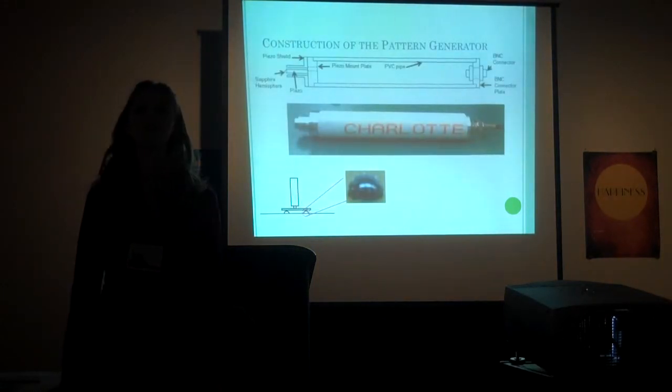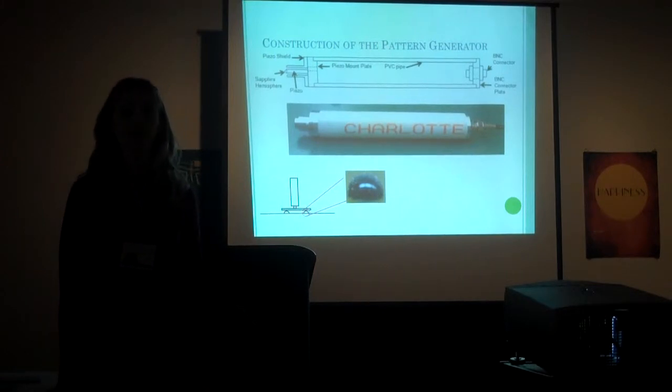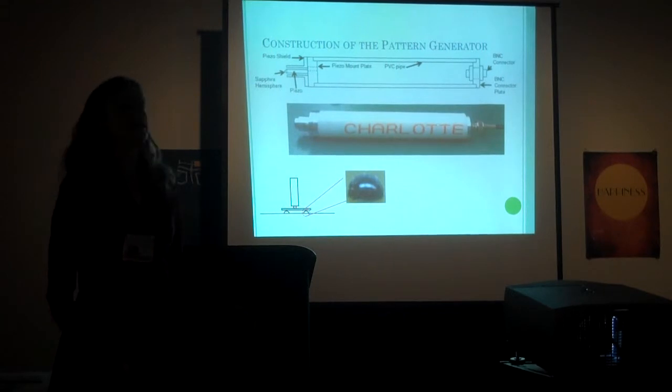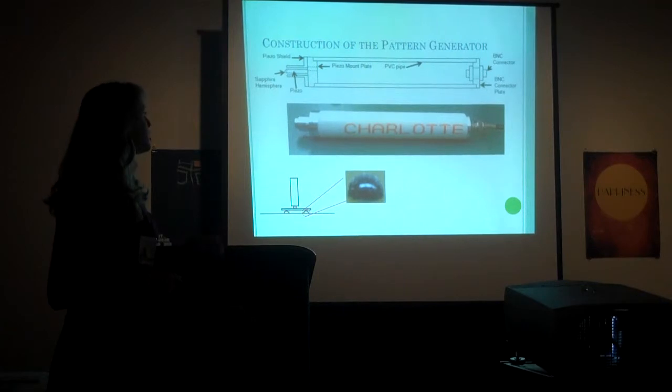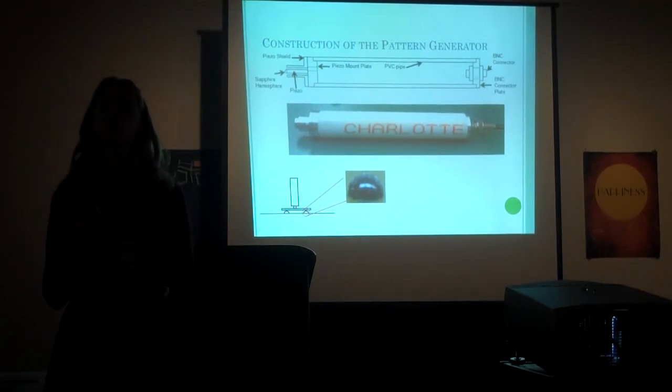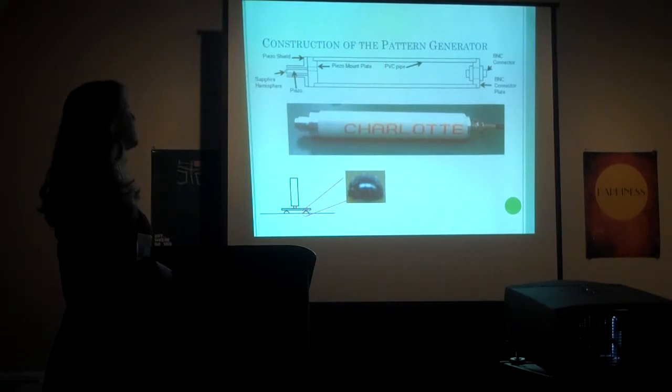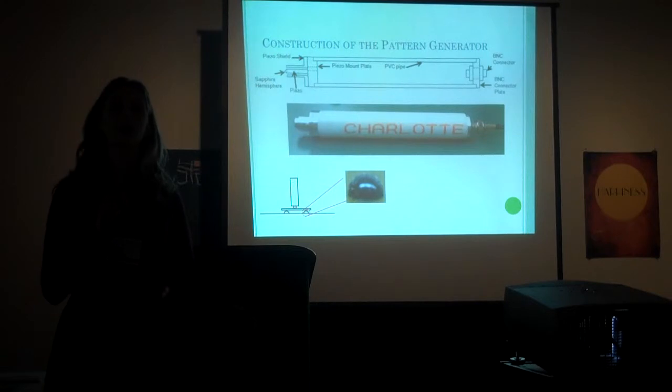Our pattern generator is based upon a piezoelectric motor device. A piezoelectric motor device is about 1 inch tall and has a very small cross-sectional area. So it receives electrical signals, and these electrical signals will cause the motor to move in and out. And you will start getting vibration of the plate. Because we needed a very small surface area, exactly 1 point, exciting the plate, we have a little sapphire hemisphere that has been epoxied onto the edge of that motor.